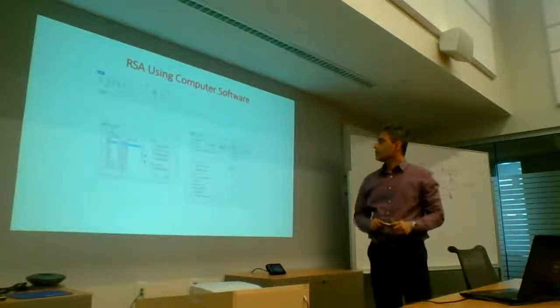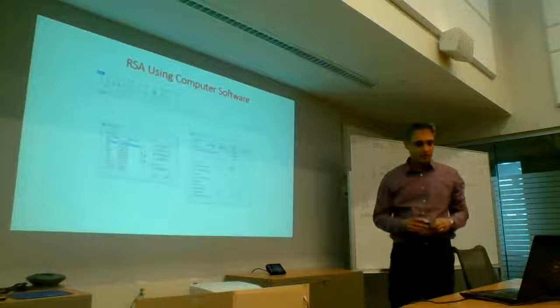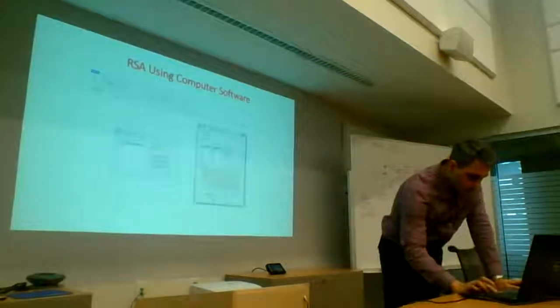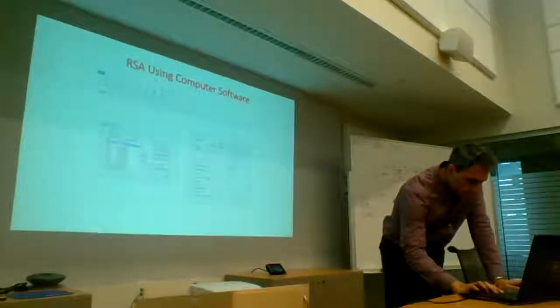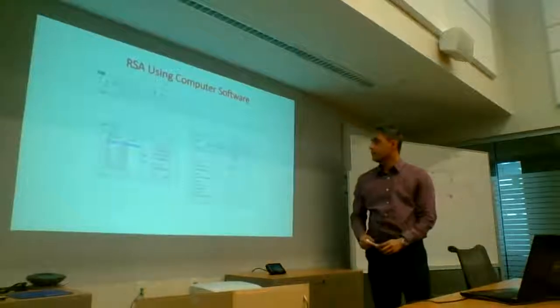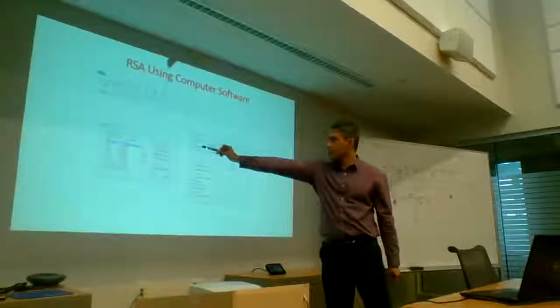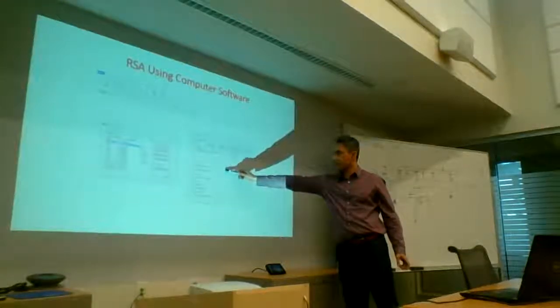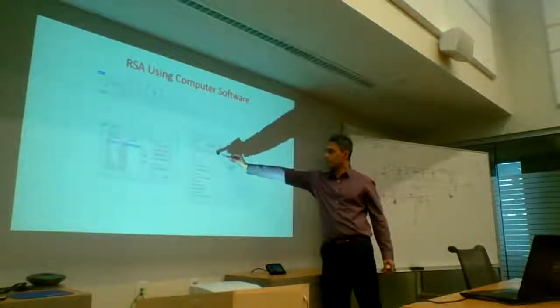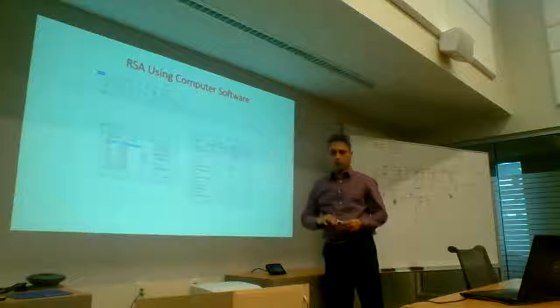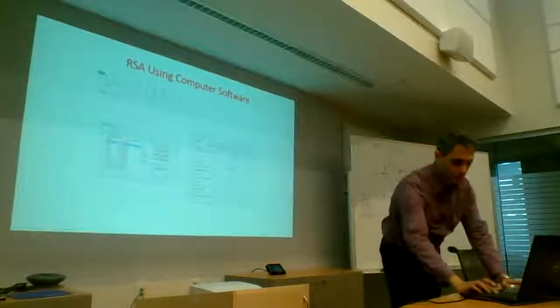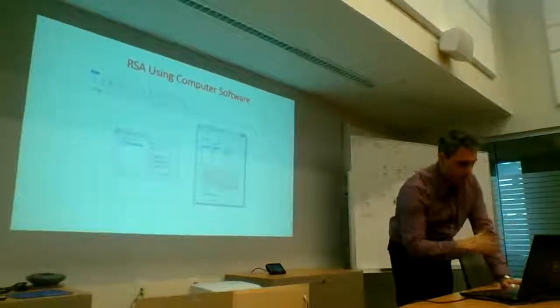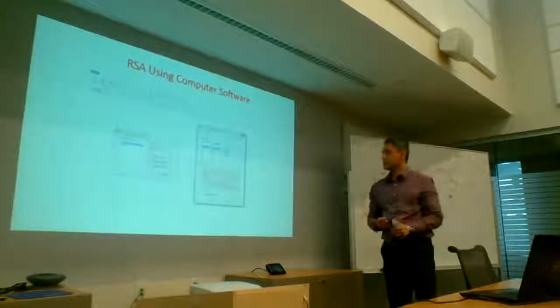Okay, I want to quickly talk about doing it using software. This is not very clear, but you basically have to set up a modal load case, and you can have a number of modes defined. You always start from a zero stress state, so don't put any load on it. You're assuming that it's not loaded. All the mass is there, but it's not under a stressed case.